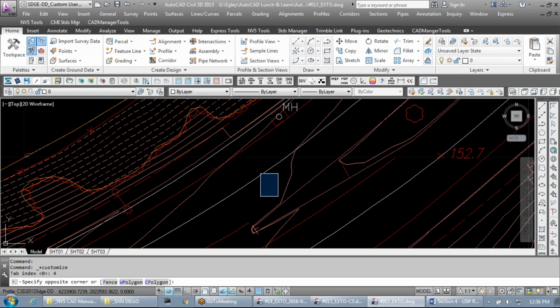Like DDV, right? You guys know what DDV is, right? To rotate your plan view according to whatever you want. That's a LISP routine. It's NV5 specific, or one that we use. I don't think we actually created it. But you don't have to load that, right? You never have to go APPLOAD and then find the LISP for DDV, right? It's part of our script that loads up.